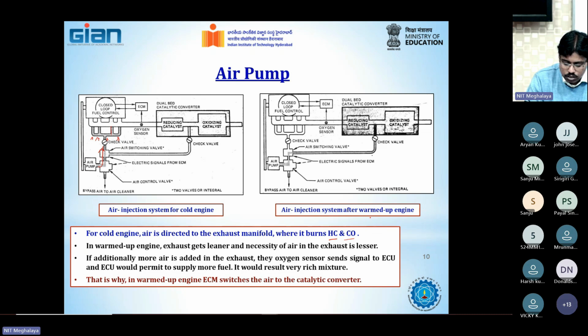Now, in case of warm up, this is good when you are operating at low speed and low load. At this low speed and low load, basically during warm up, idling, and slow speed, you run with a rich air fuel mixture. So when you run with a rich air fuel mixture, the exhaust, that means hydrocarbon and carbon monoxide which is coming out, is burned out with the help of the supply of air in the exhaust manifold.